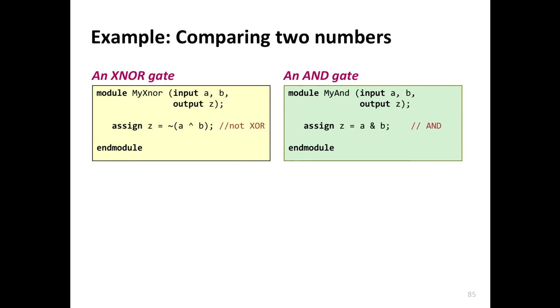So in some sense, XNOR determines equality, and XOR determines inequality. Simple. And if you want to know exactly what XOR does, it's Y equals A prime B plus A B prime. This is the actual XOR computation. Okay?